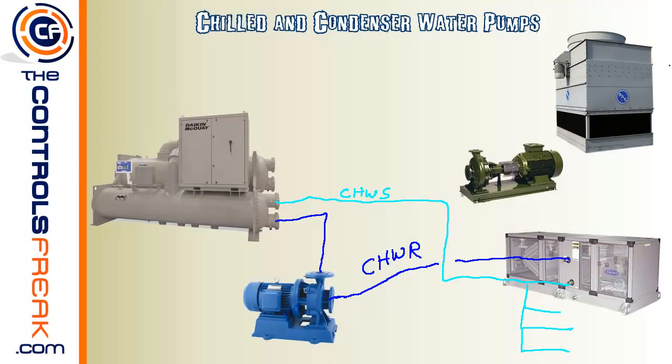On the condenser water side, you'll have the hot water coming out of the chiller. And we're going to draw this one as if it's coming into the pump. And it's going to come out of the pump and come into the top of the tower right here. So that hot water is going to come across and get cooled down with the fan on, back into the basin, and from the basin it's going to get sucked back out and come back into the chiller right there.